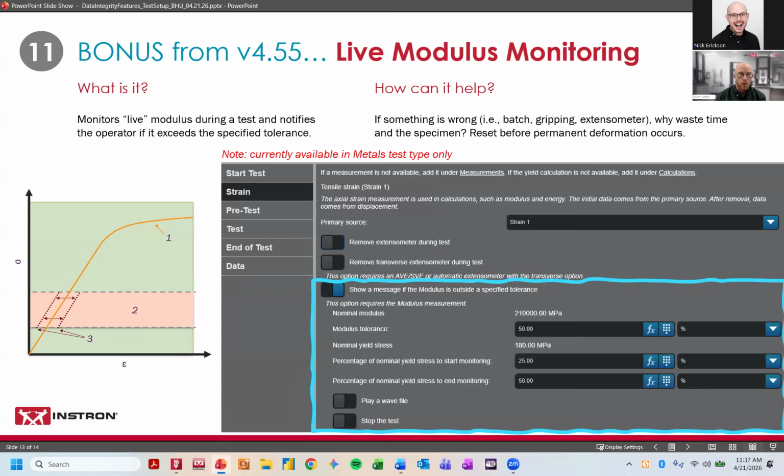So typically, if you're going to have some sort of wide variance of modulus, especially within different types of metals and metals tests, I mean, even anytime that you're measuring modulus across a batch, if there's a huge dispersion of that, then likely something is wrong.